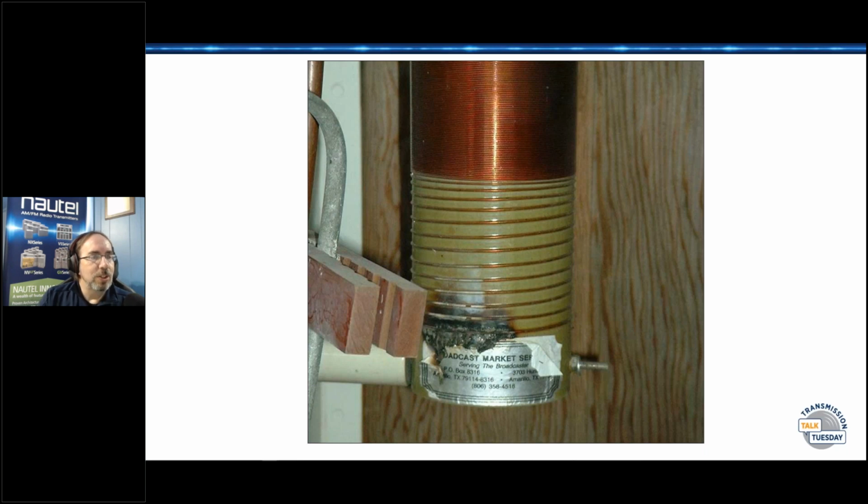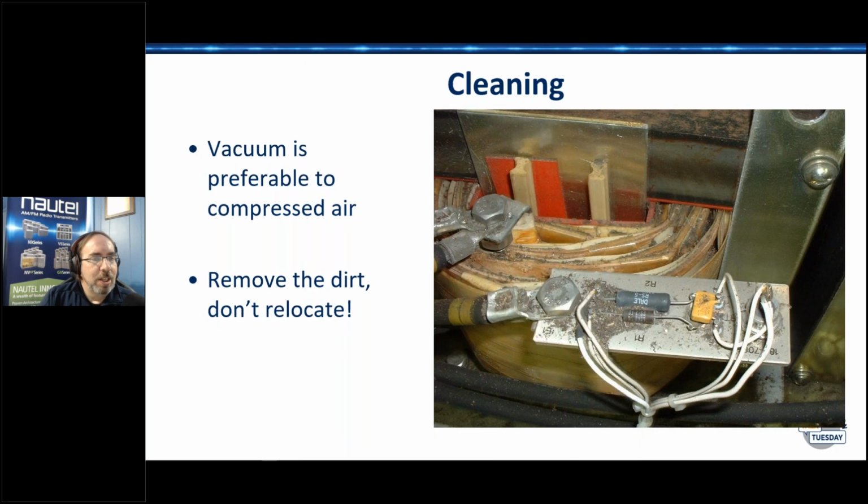What we're looking at here is a static drain choke on an AM tower, and I know Don Jones isn't online today, but that's his old company there, so that dates how old that photo is. One other thing that we didn't really touch on, somebody mentioned having the shop vac as a crucial piece of site equipment. And that is a big, big deal.